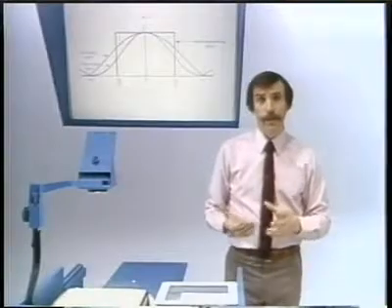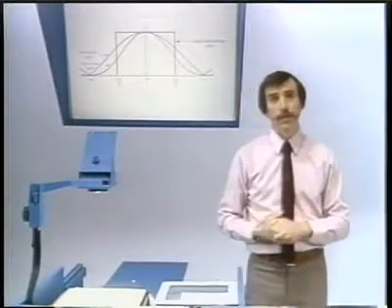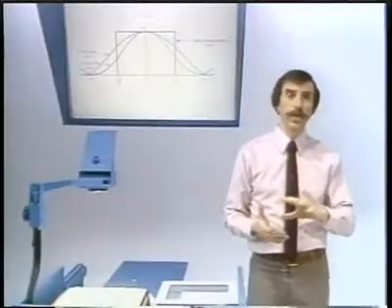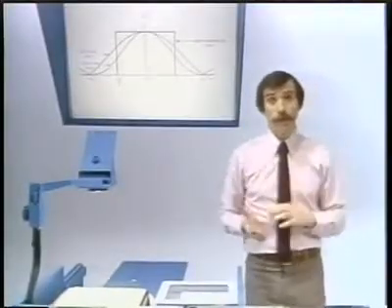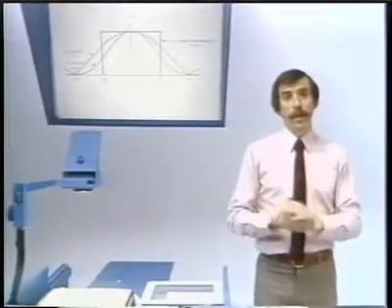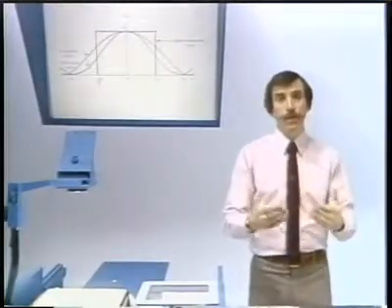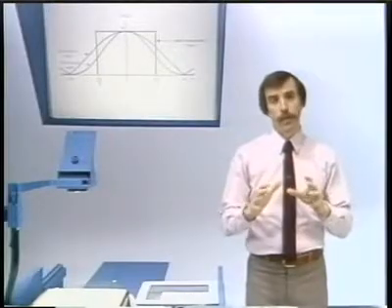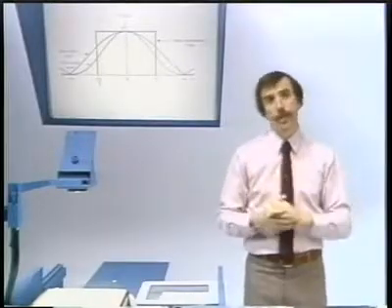Now, in fact, in many sampling systems, in any sampling system really, we need to use some approximation to the low-pass filter. And very often, what is done in many sampling systems is to first use just a zero-order hold and then follow the zero-order hold with some additional low-pass filtering.